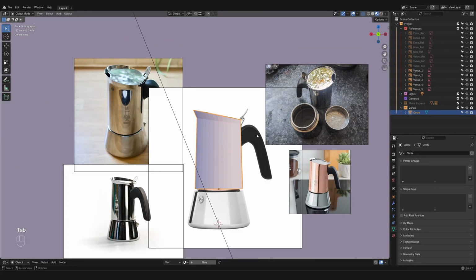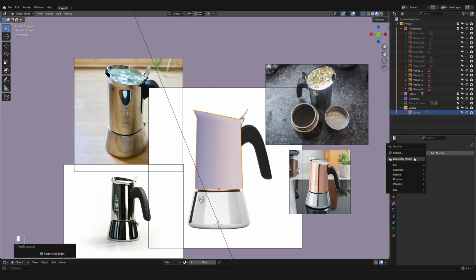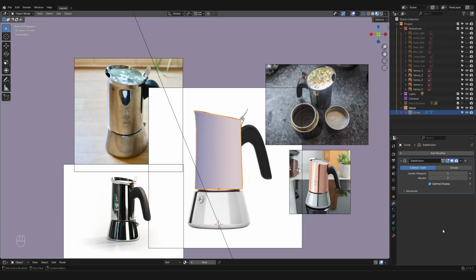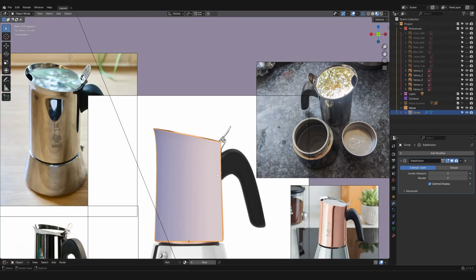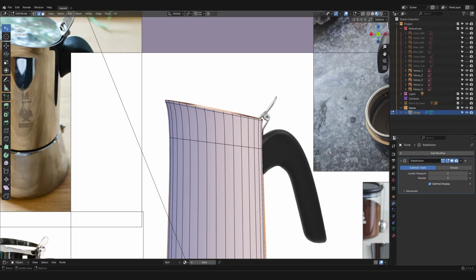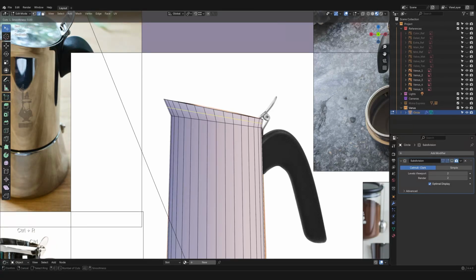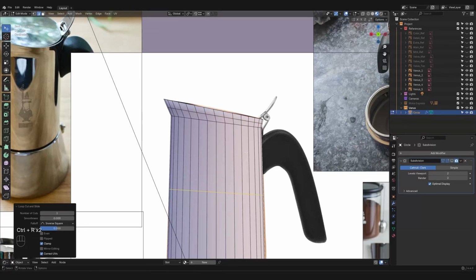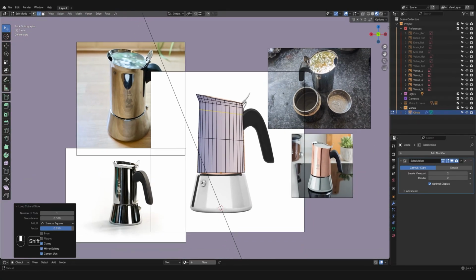And I'm gonna press Tab to go in object mode, right click, shade smooth, modifier, add modifier, generate, subdivision surface. This is gonna smooth things over a little bit, but we will need some more edge loops over here. I don't need the X-ray anymore. And to avoid confusion, I'm gonna deactivate it for a minute. Control R, edge loop, Control R, edge loop, Control R, edge loop, and this time I'm gonna bring it up to, let's call it 1.85. Let's check it, and that looks good.